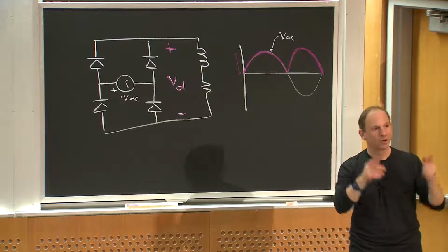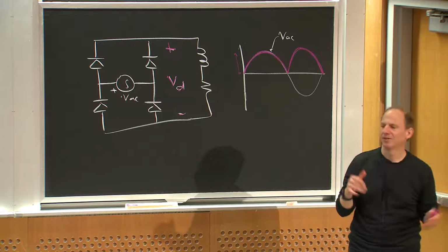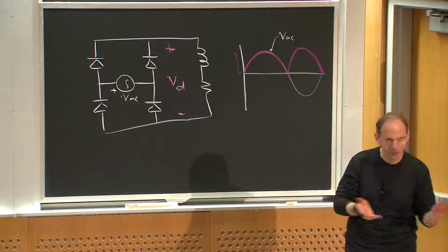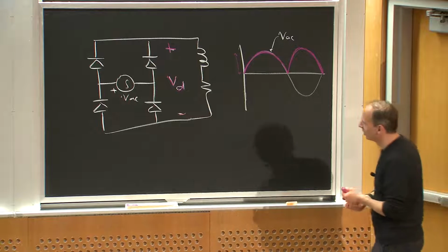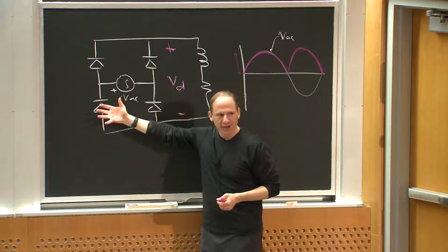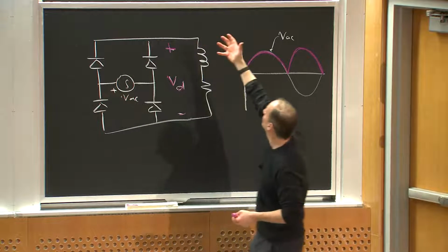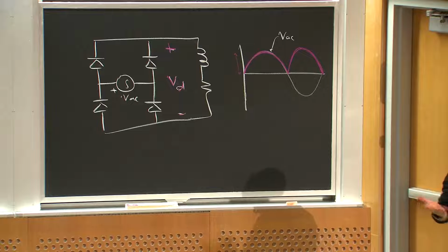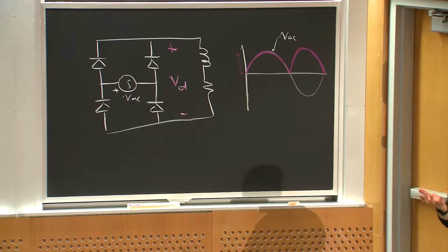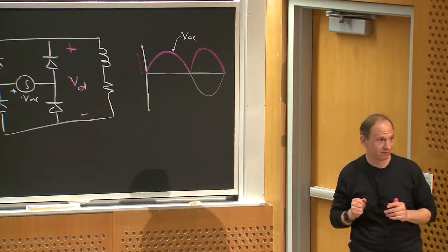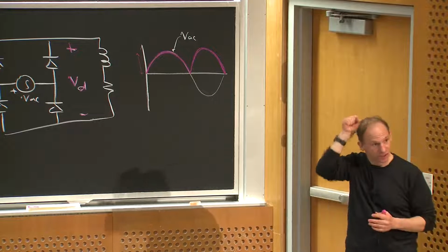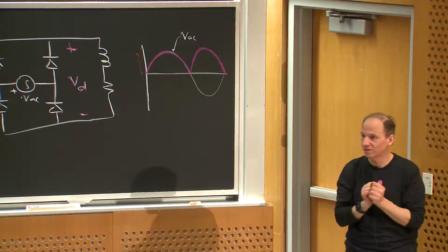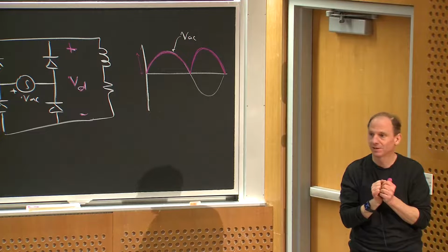Okay. What did it cost me in terms of devices? Now, it's risky just counting components, because not all components are created equal. But roughly speaking, to do the single-phase one I needed 4 diodes. To do the three-phase one, I only needed 6 diodes. So I swapped 4 devices for 6 devices, admittedly of slightly different scale. But suddenly I get much, much nicer performance, right? Everything becomes good in terms of the output filter. And that inductor is really big, it's low frequency, I would usually need a really big single-phase inductor. For a three-phase system, I need a very small inductor. Any questions about that?